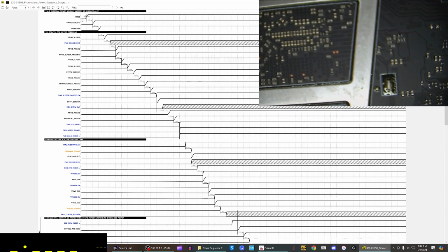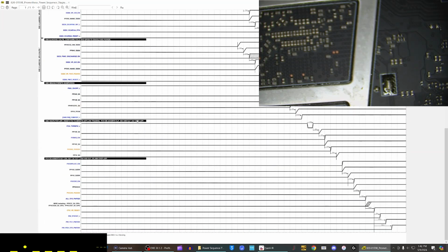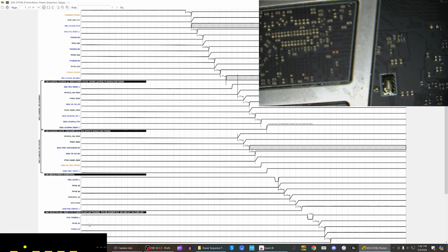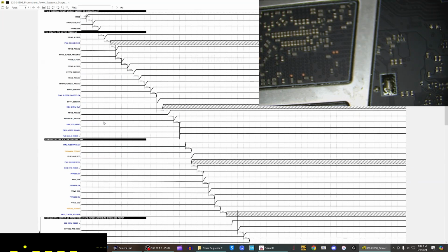Right, so when we have, you think of it as a bunch of lines. We go all the way down, really there's hundreds of lines, but this is like the machine's on, we're unlocked when we're in this area. Obviously we're going to have more current here because it's not only powering this line, but it's powering everything on before it. So if this first line or something is shorting, we're not going to get a lot of current because basically zero lines are getting powered, or a couple.